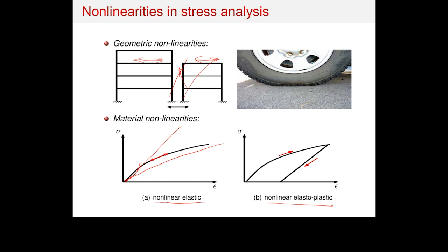But there will be one way to treat this nonlinearity and just solve for the exact curve. And this is what we are going to discuss today. Now, this is called nonlinear elastic because when you load and unload, you go back to zero deformations. This is the major difference between nonlinear elastic and nonlinear elastoplastic.